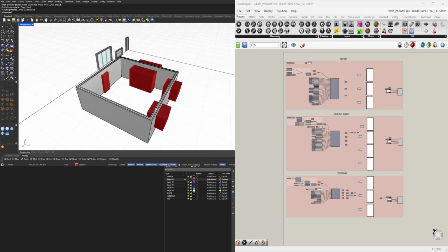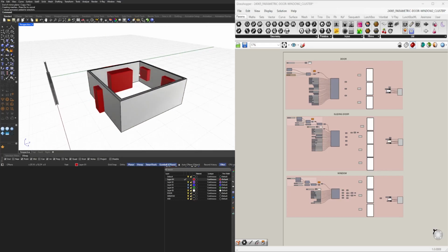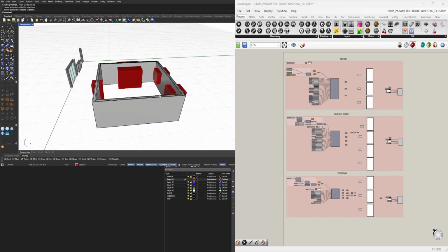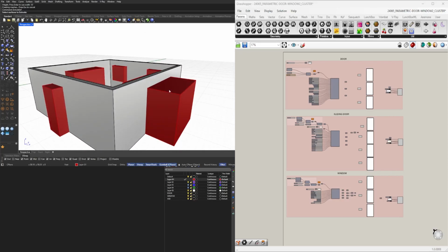So these will be fixed windows, and then on this one, or maybe those are sliding glass doors, and then this one is going to be a bigger window. So a box centered from the midpoint, 12 foot, and then make it 10 foot tall. And then I'll extrude this surface down by 8 foot.